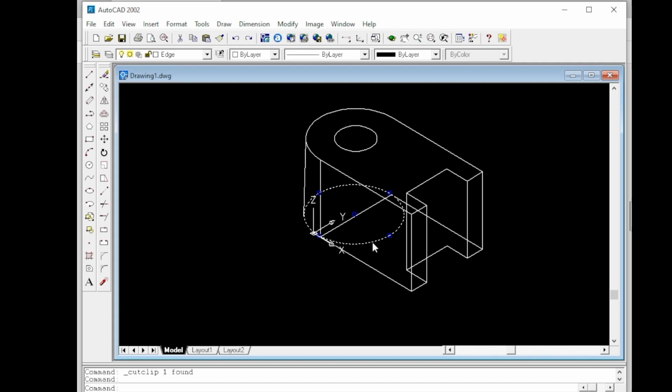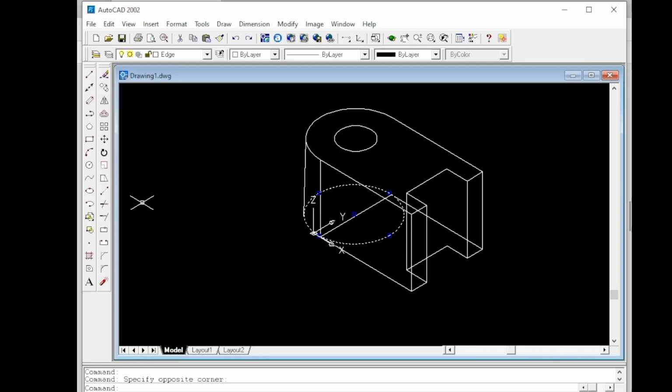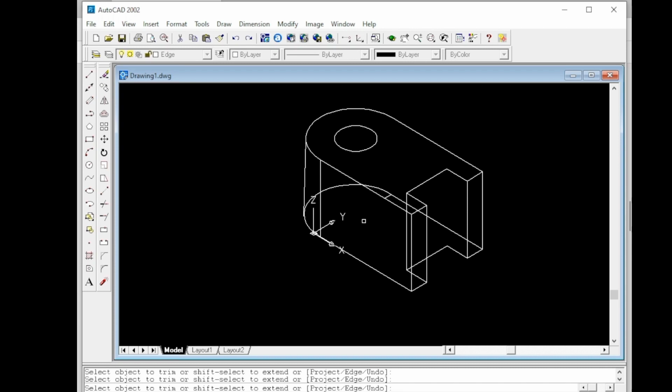So you make sure you erase them, you right click just to delete them, or you can cut. But any line or angle attached to the edge, you can use trim. Now for this case, the lower part I will use trim to remove some parts. So I'll pick the trim command, then right click, then left click on the lines you want to remove. Left click, you see.